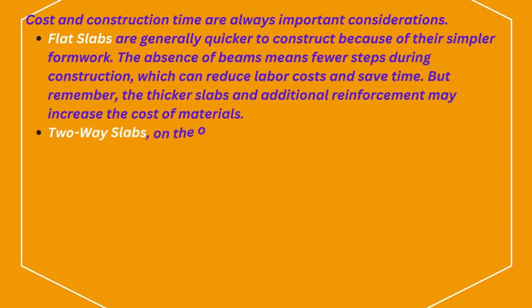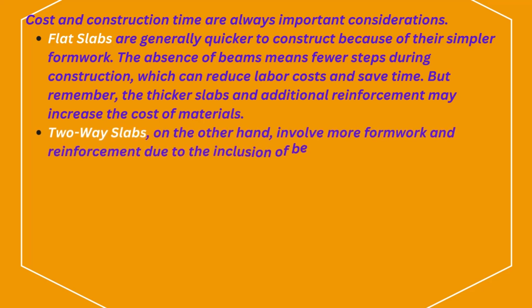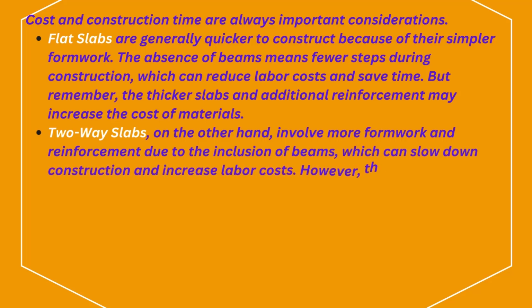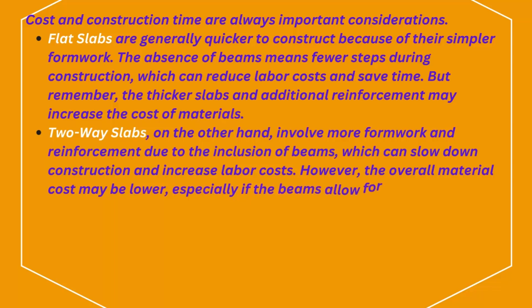Two-way slabs, on the other hand, involve more formwork and reinforcement due to the inclusion of beams, which can slow down construction and increase labor costs. However, the overall material cost may be lower, especially if the beams allow for thinner slabs.